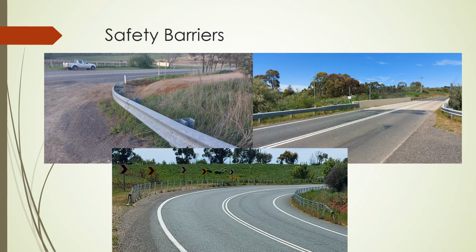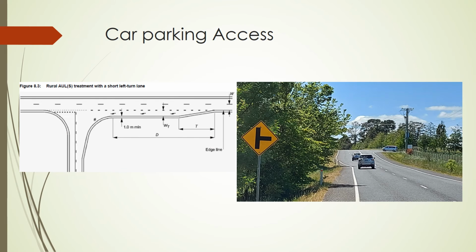The problem is when those barriers are impinged, they can actually present a bit of a hazard themselves, in the fact that they won't stop vehicles. So that is an issue with regard to selection. Neither wire rope nor the steel beams allow pooling of cool air or moisture behind them. So in a cooler climate like we're in, they are the preferred option over the concrete barriers. And in this case here, we're recommending that council adopt.